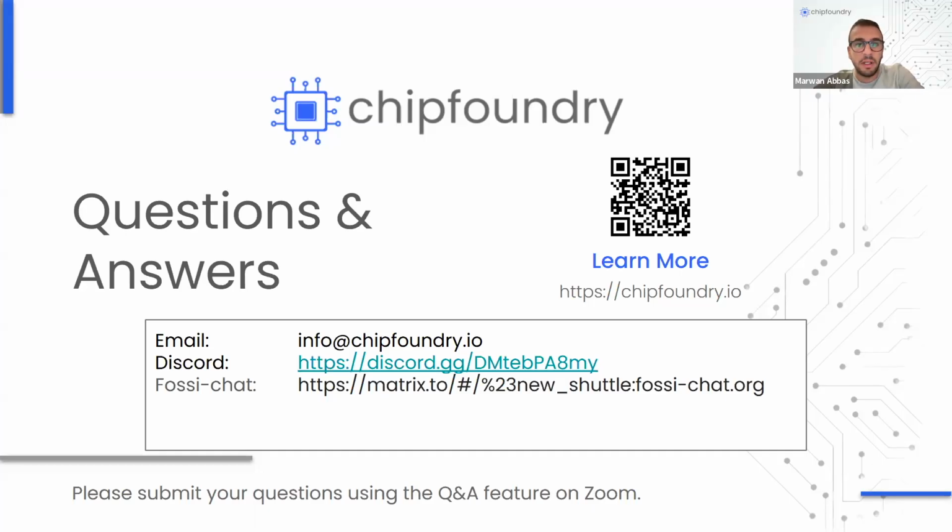How many levels can be used for each bit? Yeah, so that's a very good question. The prototype IP currently is for 1 bit, but the user can play around with it and achieve higher bits if they need. But 1 bit is guaranteed in the IP. It's like a synapse, right? So they can play with the duration they're programming each cell. We give flexibility to program the row and column with the data they want to program, right? So they can try multiple bits if they need.